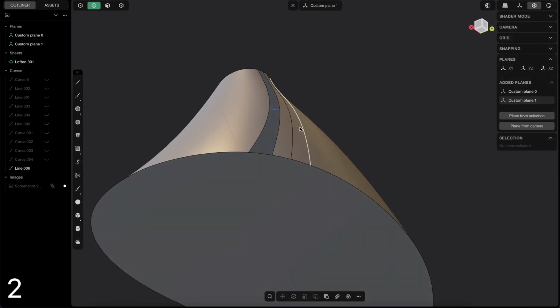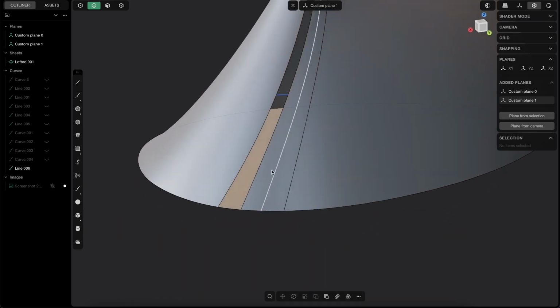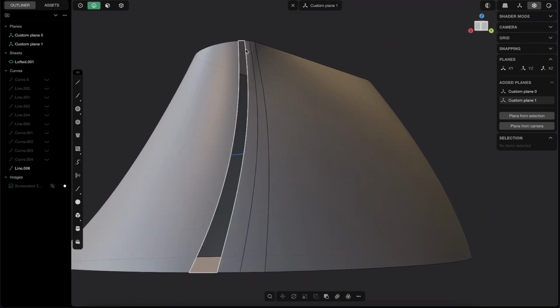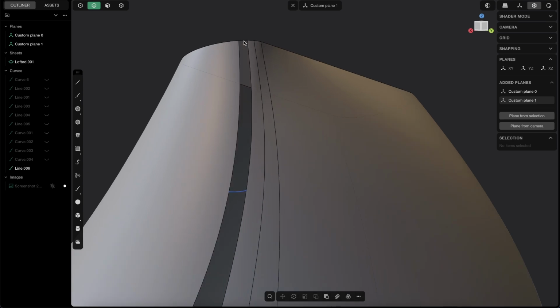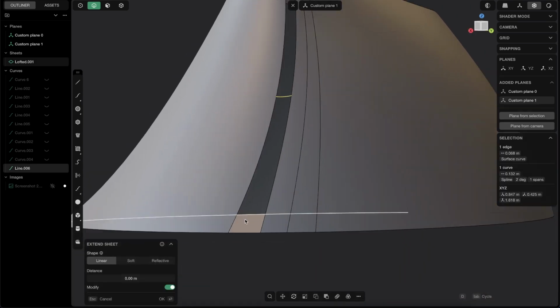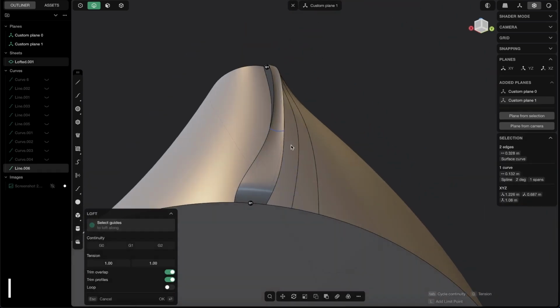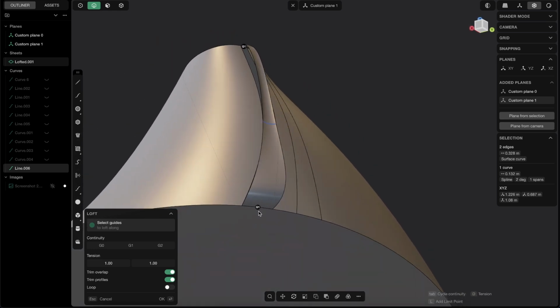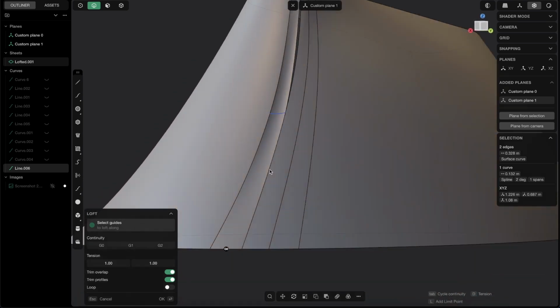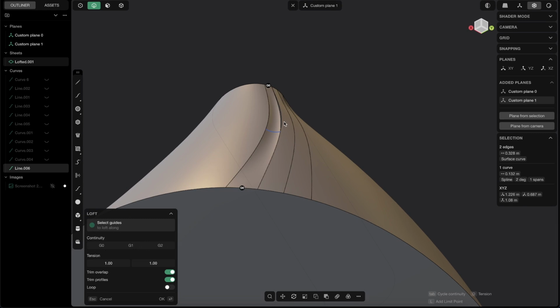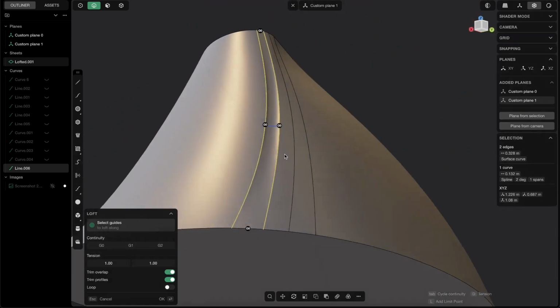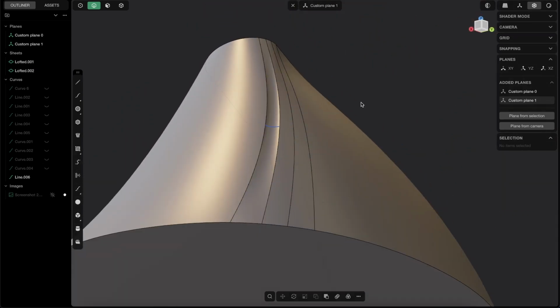And now, very simple, you just need one curve. Now again, press 2, edge mode, and just select this edge, this curve with shift click, and this edge again, and loft it, right? Now you see we already get something, but obviously we don't need any tangency either at the top or the bottom. So just press tap and tap, so G0, and voila, now we are getting somewhere, but obviously we have to add those edges. So shift, and again, just give it G0 everywhere. And voila, it works perfectly.